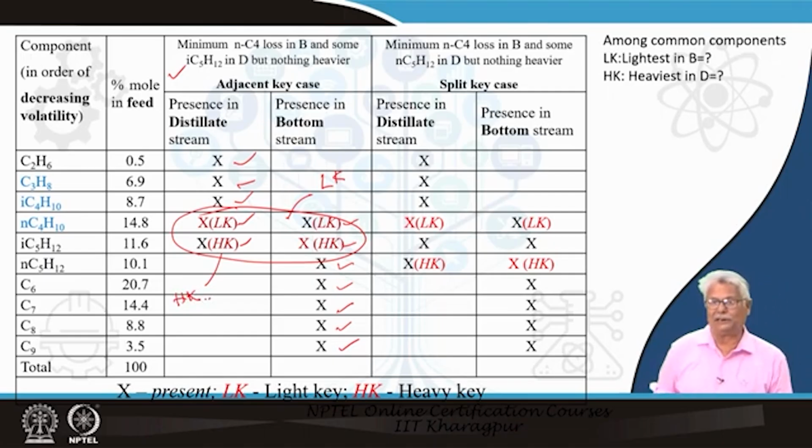Now, the same separation, that means with the same feed, the top product being LPG again, which is expected to be primarily C3 and C4, I consider it a different case. What do I have here? I am going to accommodate a certain amount of NC5 in this also.